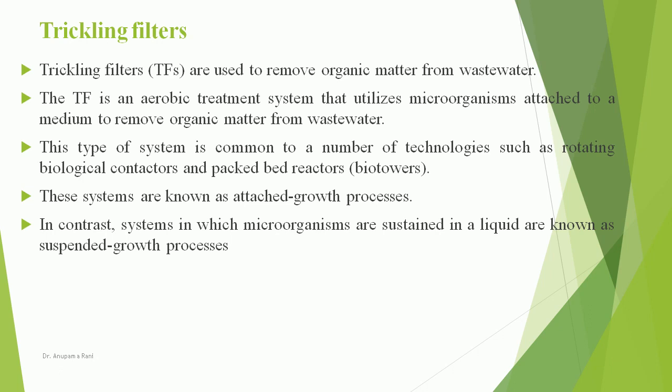This type of system is common to a number of technologies such as rotating biological contactors and packed bed reactors, biotowers. These systems are known as attached growth processes. In contrast, systems in which microorganisms are sustained in a liquid are known as suspended growth processes.